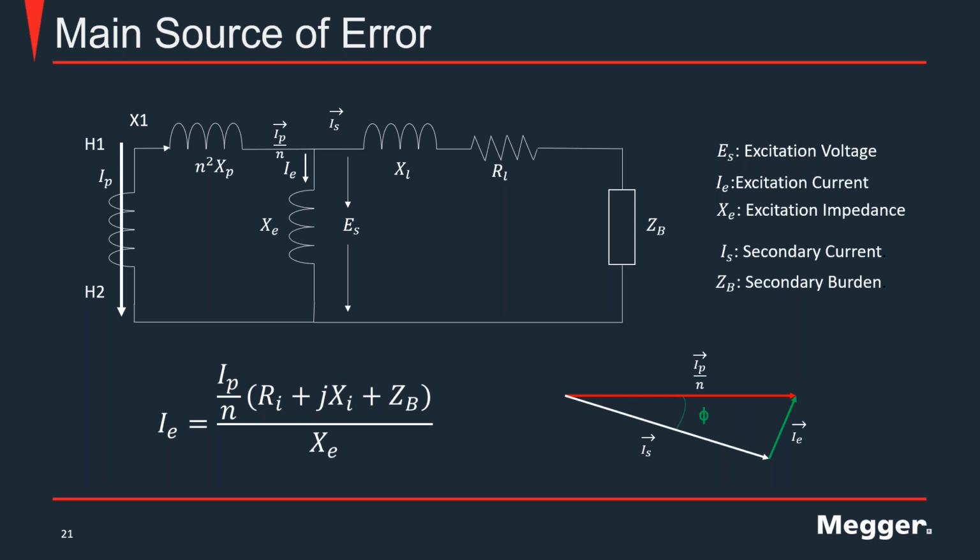So since the accuracy requirements for a protection CT are not as stringent, you can allow for a higher burden and a higher error, given that you're looking for the ability to measure at those higher currents. I guess that would be the answer to it. All right, awesome.